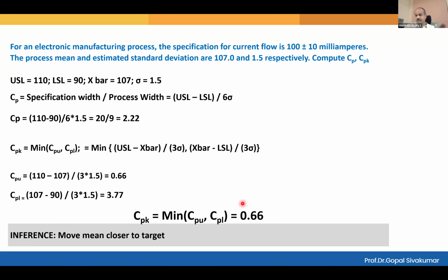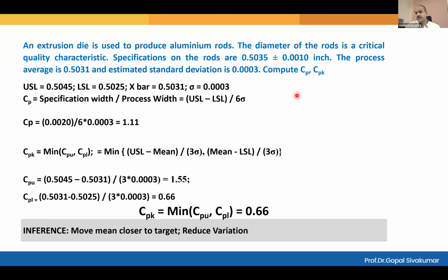So the consistency is appreciated, but at the same time, we want the candidate to always score good marks. So you have to improve on the CPK, which means you have to move the mean. The mean is now on the bad side. Now pull back the mean, bring it closer to the target so that your process will start delivering the needed result. All of you, do you understand this? Yes, sir. And you can apply this knowledge wherever required, but the condition is measurable characteristics.